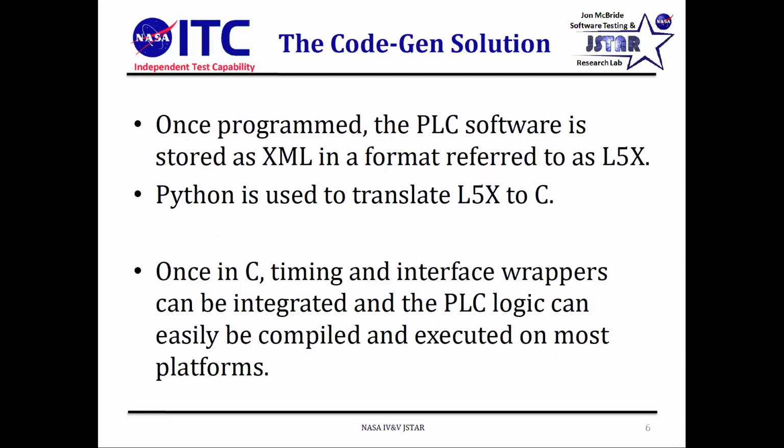So what did we do? We decided maybe we can take this ladder logic, and Michael will get into what that actually means in the future slides, and translate it into some other language that we can actually run. When we started looking into that, we found that what's saved when you write your ladder logic code gets stored in an XML format called L5X.